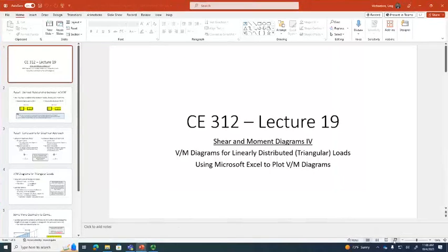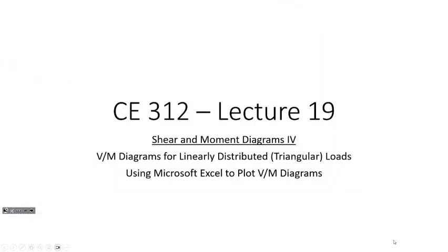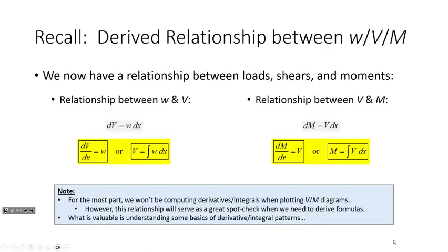Okay. All right. So what we're going to do is take our knowledge so far and extend it into linearly distributed loads. To be clear, we're using the same mathematical expressions we have so far, the same relationship between loads, shears and moments. If I integrate my load diagram, I will get a shear diagram. And if I integrate that shear diagram, I will get a moment diagram.